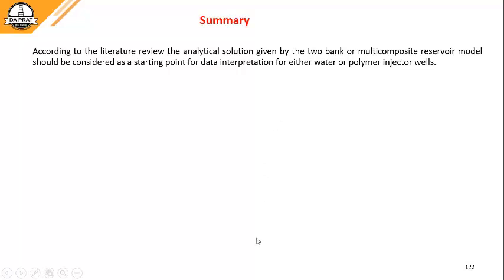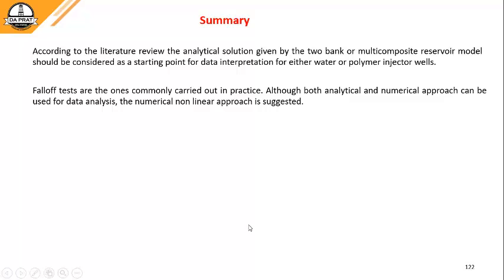According to the literature review, the analytical solution given by the two-bank or multi-composite reservoir model should be considered as a starting point for data interpretation for either water or polymer injector wells. Fall-off tests are the ones commonly carried out in practice.